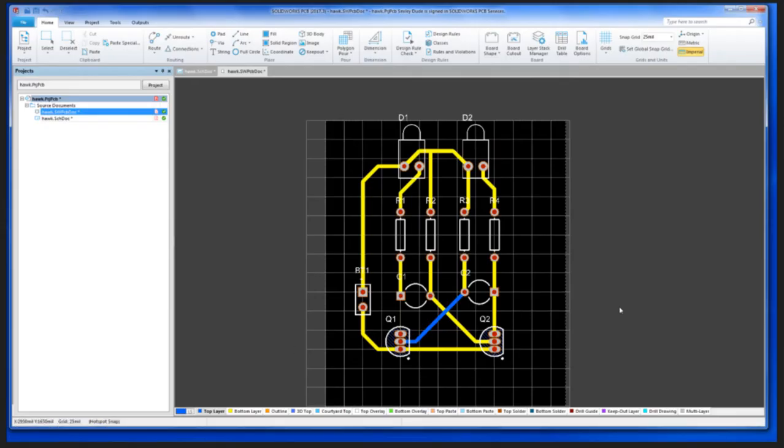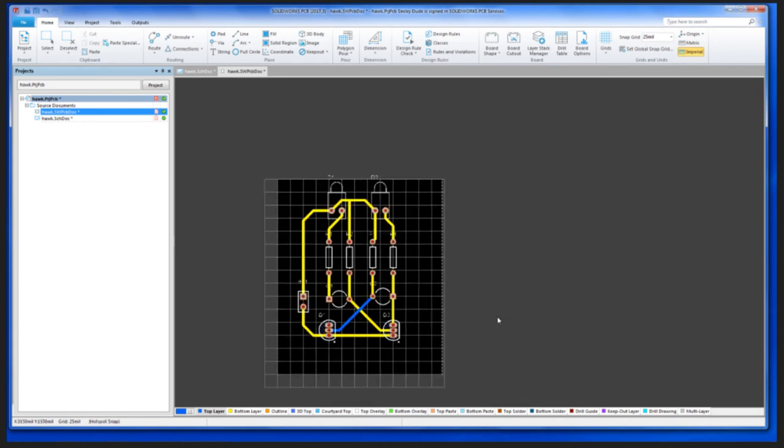So back onto our circuit board design, 2-layer board. Typically, as you know, we would have an extreme amount of documentation describing our board material, our silkscreen colors, solder mask colors, IPC specification for manufacturing. That's a lot of detail. I could certainly create that into a template and pull that into this design.